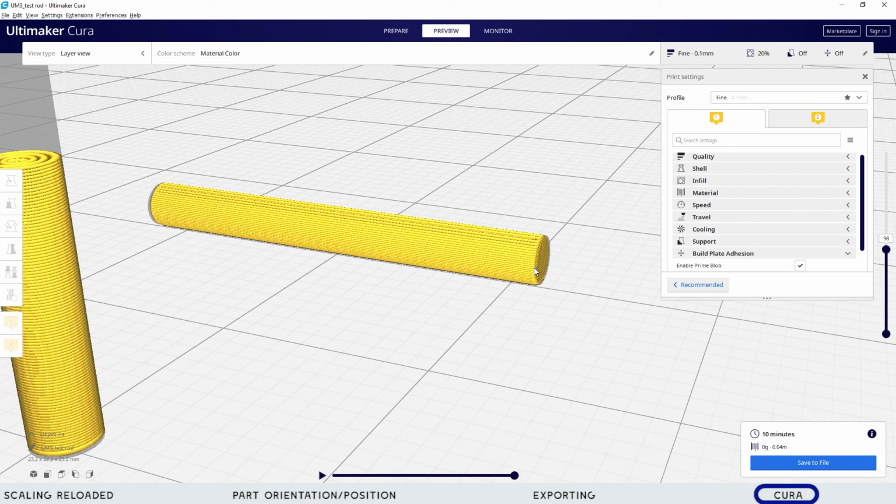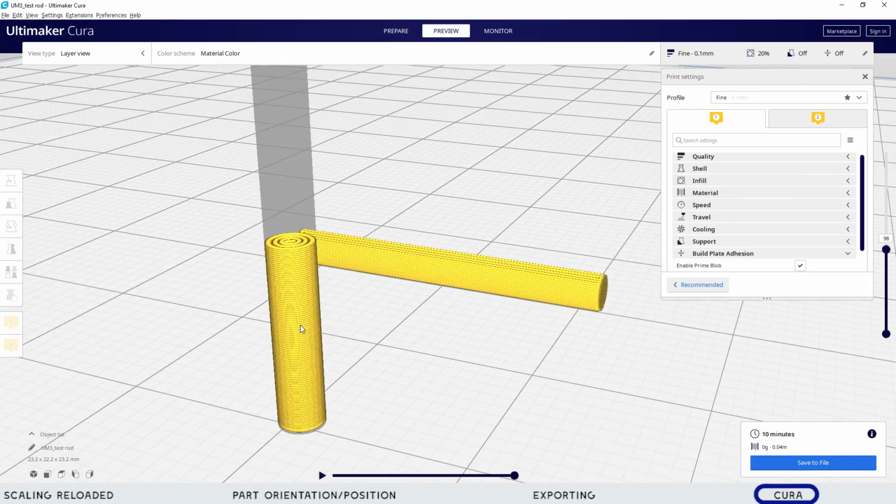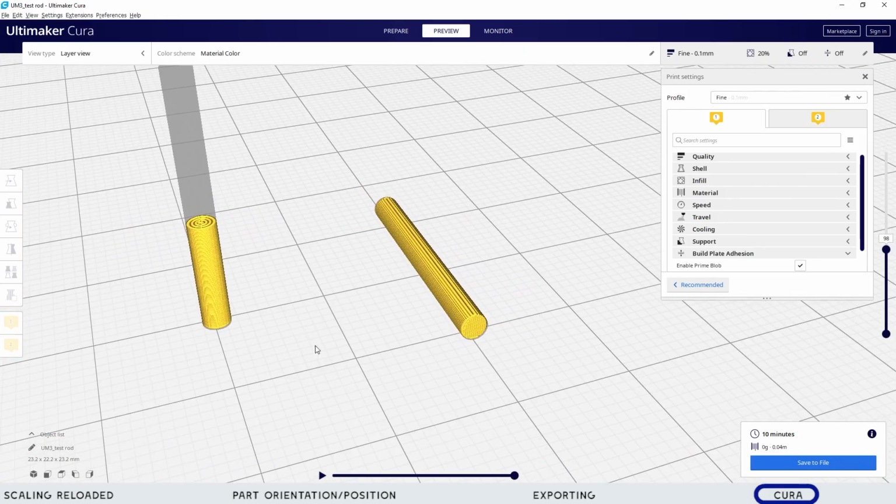Now, it may start as a single split where the force is applied, like here, and then start to run down, kind of like the wood grain on a baseball bat, say. But that's its most likely stress point that it's going to break. So depending on how you're going to use a part is going to determine how you orient your part.